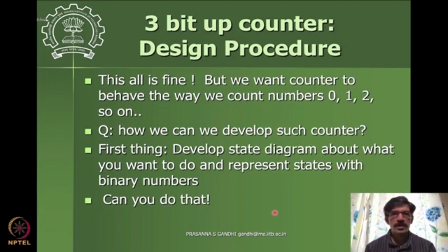Again we use the principle of state here. Sequential logic design needs the definition of states, and once you define states, the problem becomes very easy. It is then expressed as a combinational logic problem, and then we'll see how we use D flip-flops to get a circuit out of that combinational logic table.